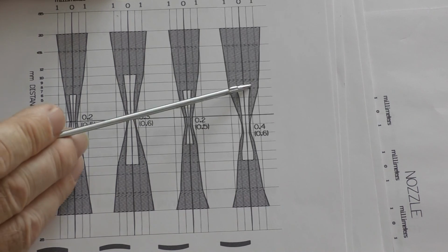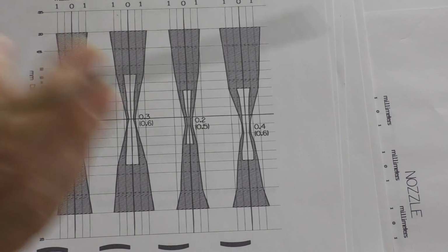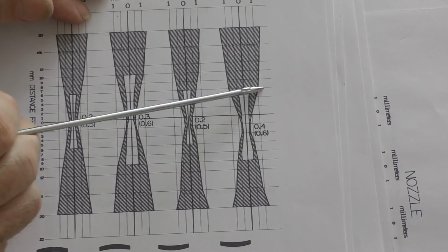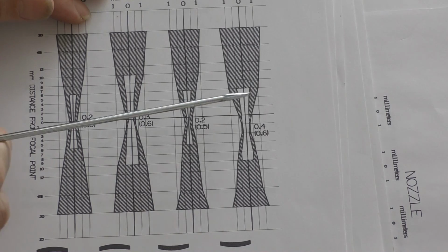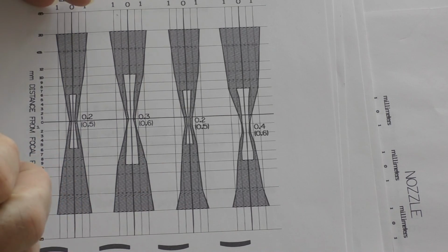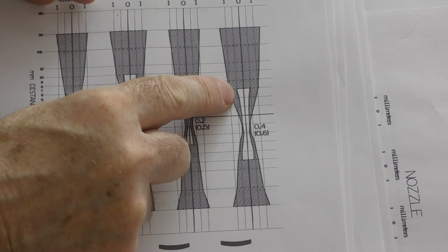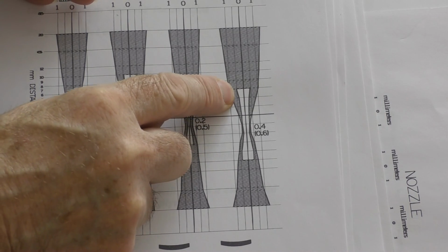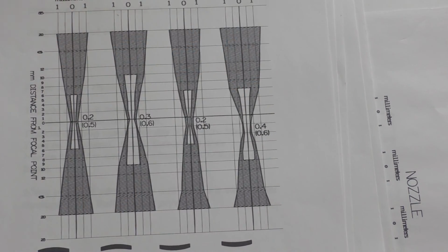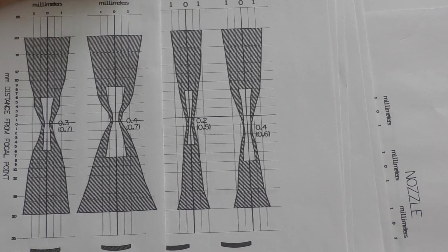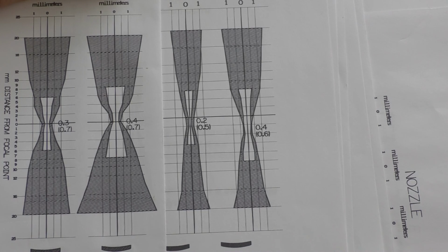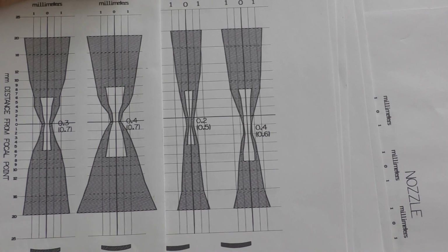So we've got a certain amount of energy in every pulse that we fire at our piece of card. There's a fixed amount of energy. It doesn't sustain itself and burn a bigger and bigger hole. It's just enough energy in there to burn that particular size hole. So I did experiment with a pulse length of 50 milliseconds. So there's 2.5 times the power in here than we've got there.